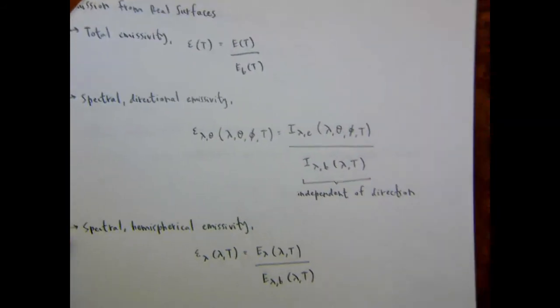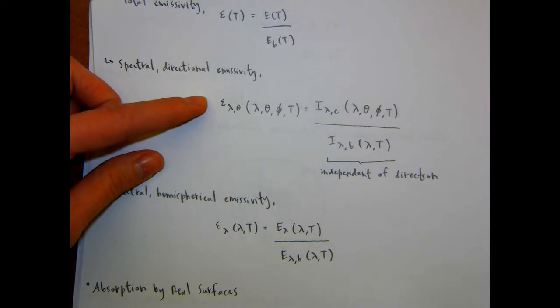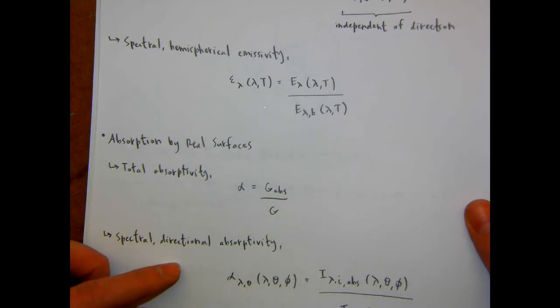And we introduced a couple more concepts to work towards that derivation. So the first concept was that radiation inside a cavity, an isothermal cavity composed of a single surface, approximates black body radiation. The second couple of concepts were that emission from real surfaces and absorption by real surfaces depends on the spectral and directional nature of the radiation. So basically we can write expressions for the emissivity as a function of the wavelength and direction, and the absorptivity as a function of the wavelength and direction.